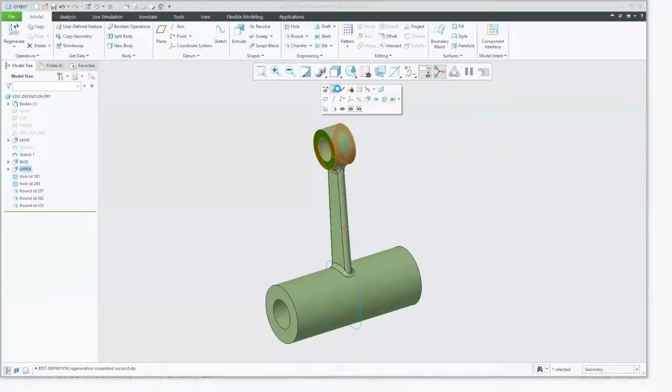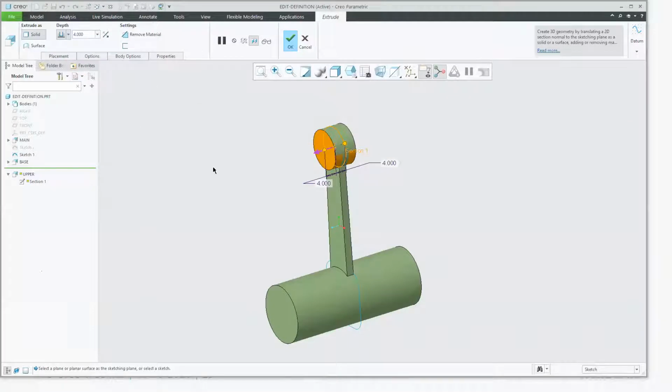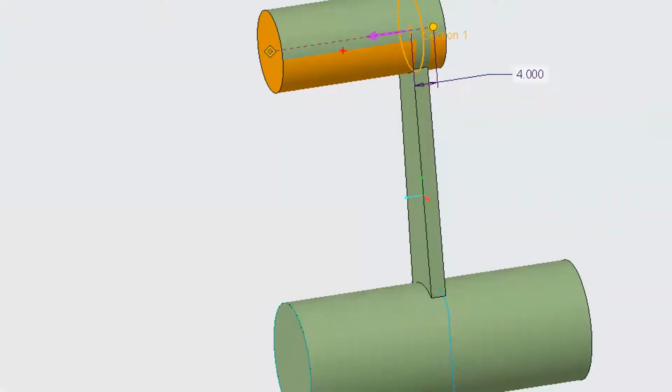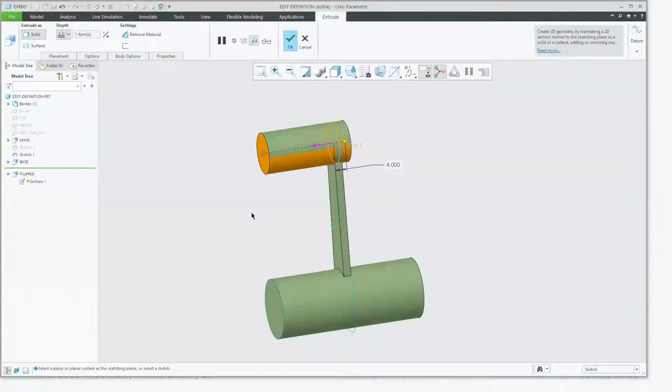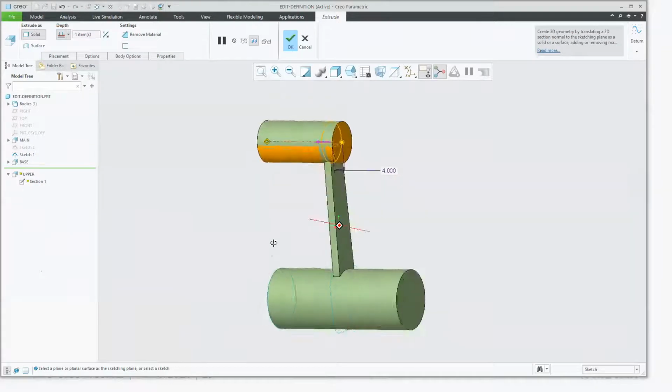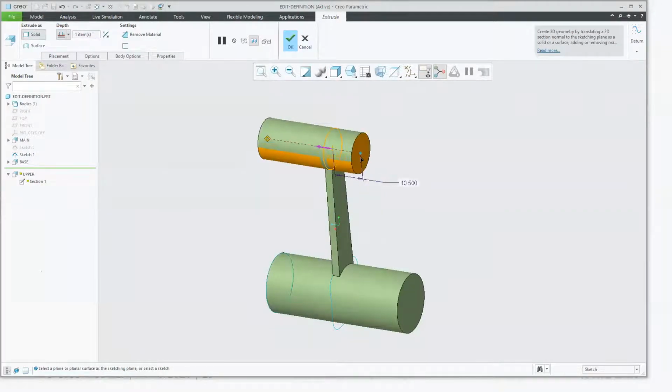And I know we could do an edit definition, and I could do that up to surface and all that. But I don't know if you've tried, since the old Wildfire days, you were able to drag that and at the same time hold a shift and snap to it. So that's a nice little thing that I like, where as you're dragging those drag handles and you hold a shift and snap, it's technically doing the up to surface, as you can see here, or to selected, really, right? So again, I'm holding down the shift as I'm dragging it, snap, boom, done, right?